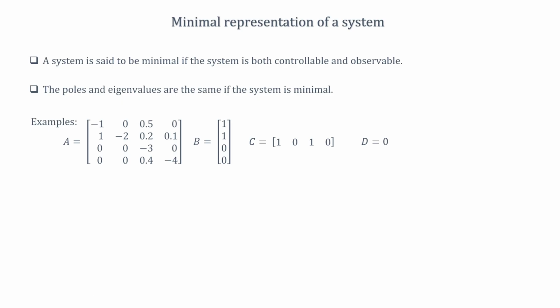What are the controllable eigenvalues of this system? The controllable eigenvalues are -1, -2. The uncontrollable eigenvalues of the system are -3, -4. Yes, so the system is stabilizable because the uncontrollable eigenvalues are on the left half of the complex plane. What about the unobservable eigenvalues? These are the unobservable eigenvalues, and both are on the left half, so that means it is detectable.